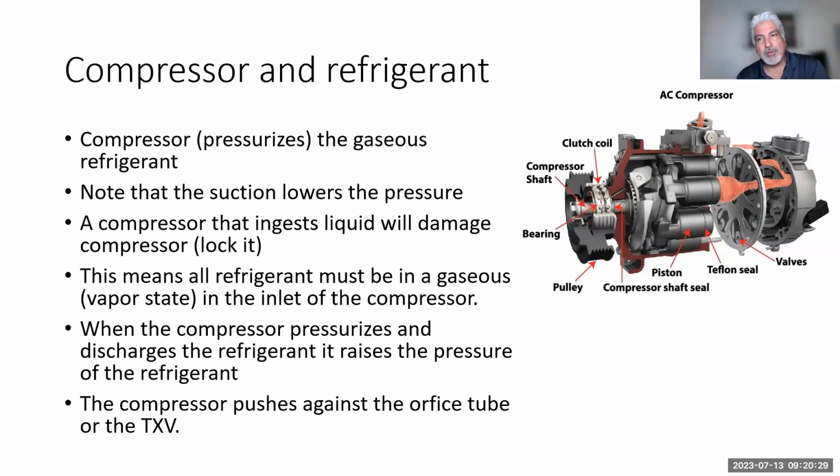But on part 3, I'm coming up with some animation here that I'm trying to get for you, is that there are basically two different styles of compressors. There's your piston style, like you can see there in the picture, with the swash plate moving back and forth. But then there's also your variable displacement compressors. In my opinion, those are the best compressors, the variable displacements. They kind of took an absence. Now they seem to be coming back. Different manufacturers used them for the longest time.